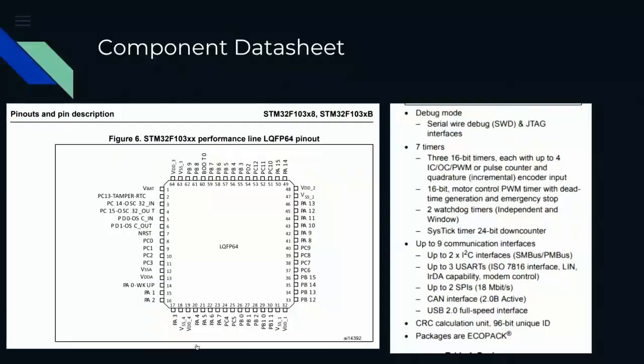Identifying signals. The first thing, if you open the device itself, is to try to track the communication and how the components are interconnected. The next step would be to pick up all the component identifiers and try to find the datasheet of that component. For instance, here's an example of an STM32 controller. You can see that you have serial debug on it. You have UART ports, you have SPI, CAN interface. A lot of those ports are configurable, so it's not necessarily there, but it's nice to know which pins are what.